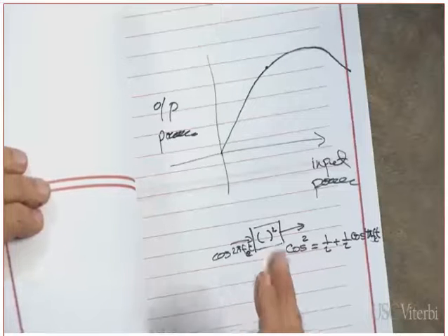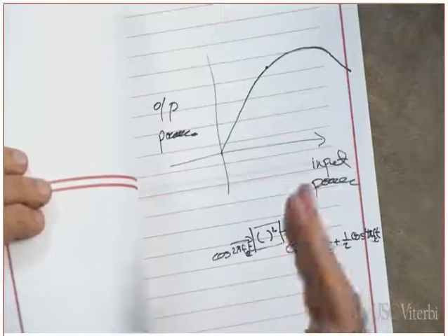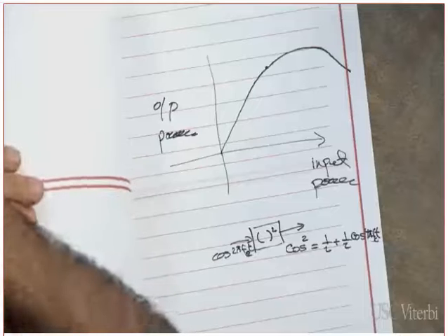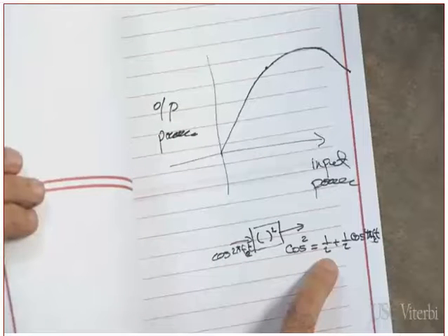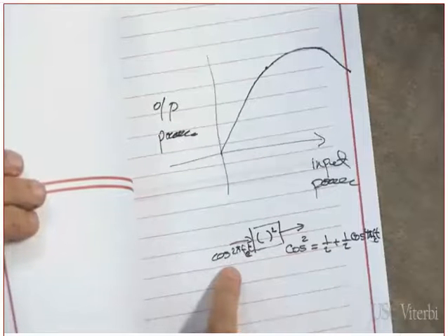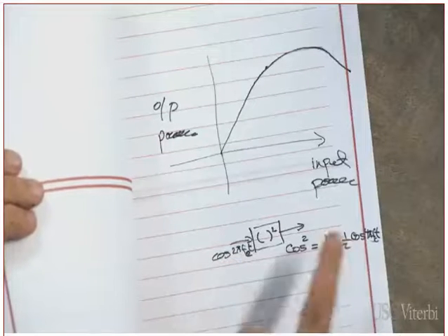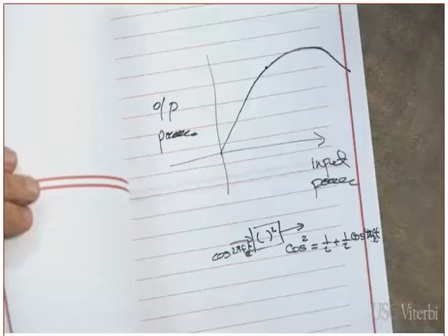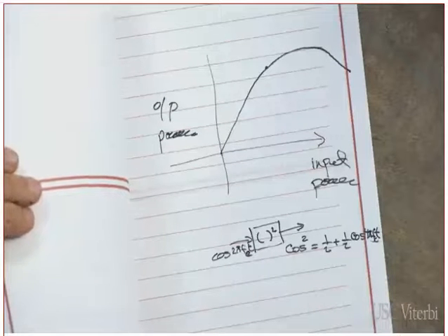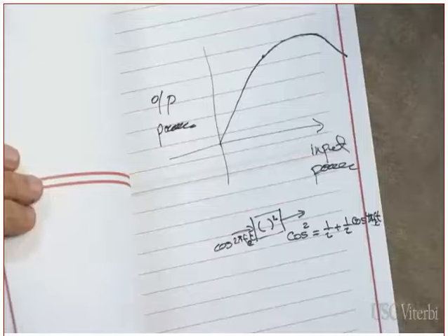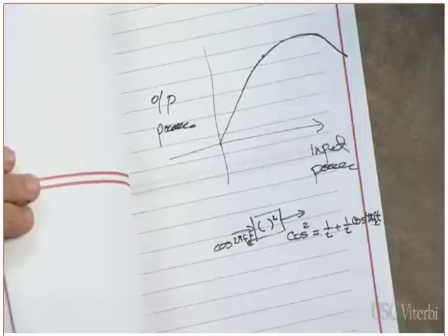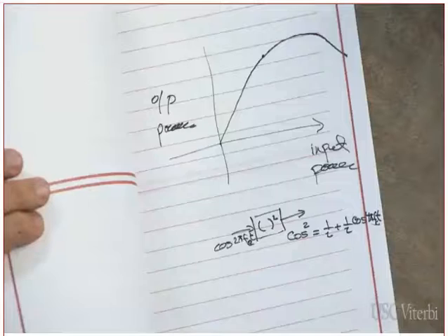This is just to show you how you know whether the system is linear or nonlinear. A nonlinear system creates frequency components that were not available at the input. Is there a DC component at the output? Was there a DC component at the input? No. It created a new frequency component. Was the second harmonic present in the input? It created it at the output. Clear? A linear system may amplify some frequencies, may reject some frequencies, may attenuate some frequencies, but it does not create new frequency components that were not available at the input.